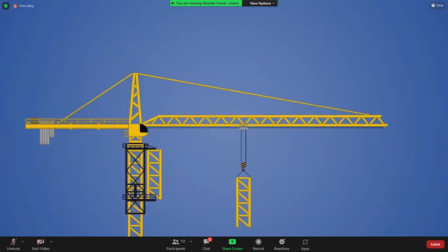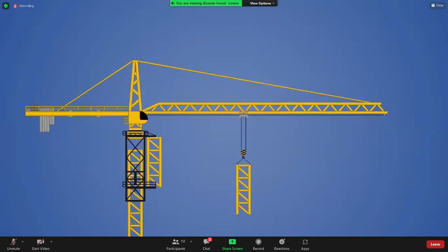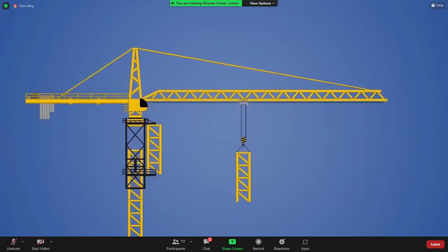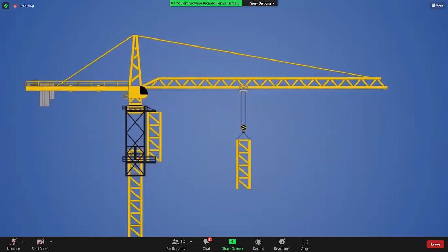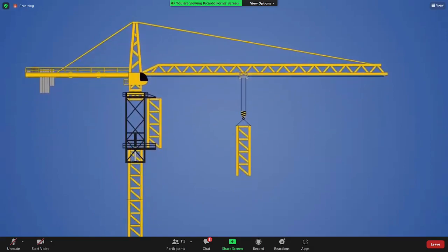Once the crane is confirmed to be in balance and all safety checks have cleared, the hydraulic cylinder is then pressurized to take the weight of the crane top, and the slewing unit is unbolted from the top of the mast. The cylinder is used to lift the climbing frame along with the top of the crane until there is enough clearance to insert a new mast section, which usually requires several strokes depending on the cylinder's length.